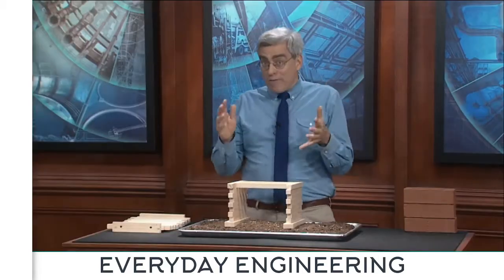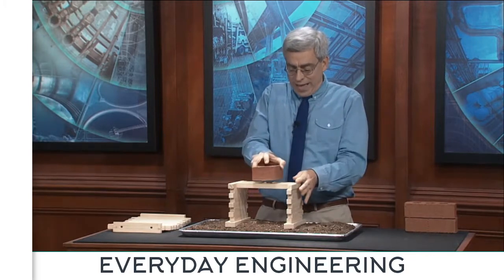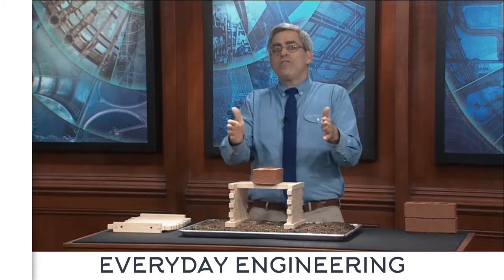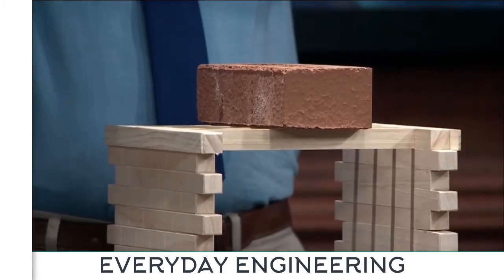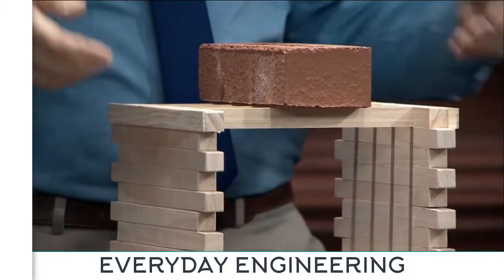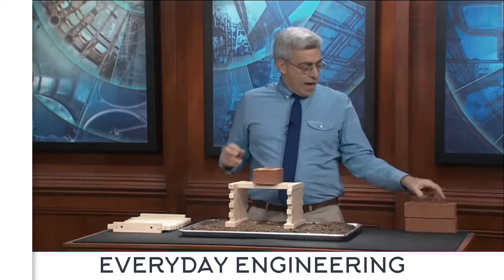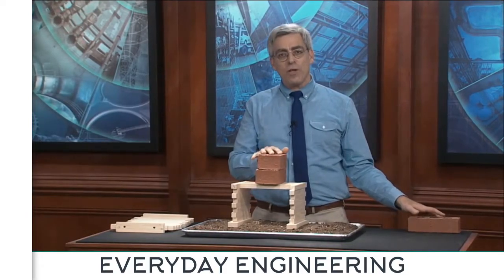Now, when a gravity load is applied to our structural system, the joists carry the load in bending. They transmit that load out to the outer perimeter walls, and the perimeter walls then transmit the load vertically downward in compression through the wall footings and into the soil below. As you can see, this is a fairly effective system for carrying gravity loads.